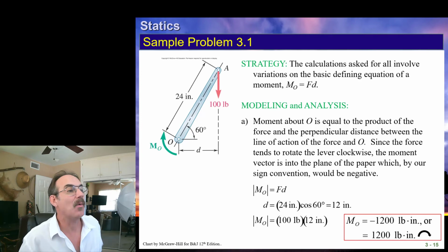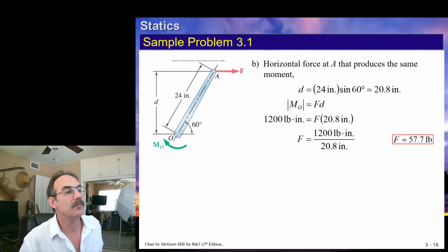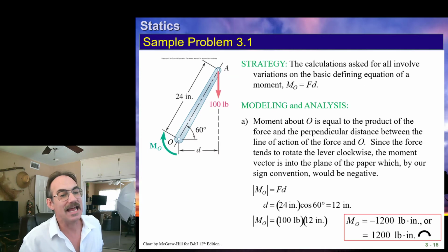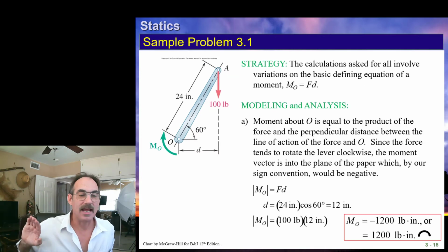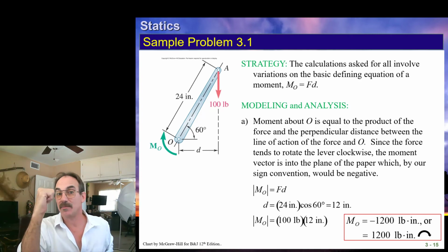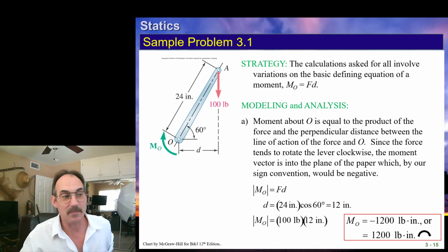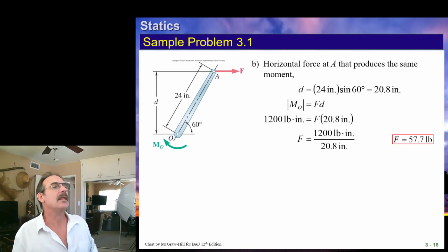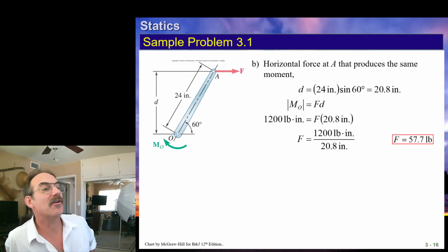And this is how that works. This is using the perpendicular distance approach. Normally we'd call this negative because when you take R cross j, you can see it's going into the page rather than out of the page. Right-hand rule, out of the page would be positive. This is looking at that further, another way of doing it.